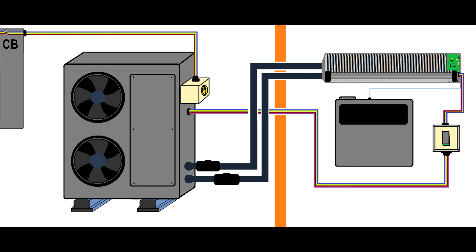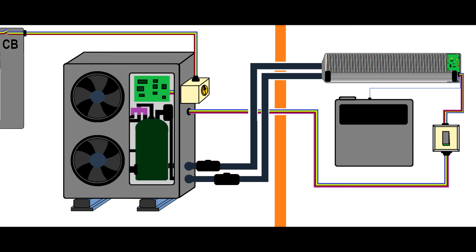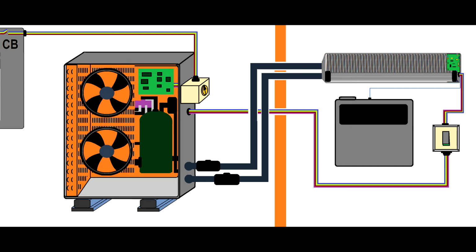If you take the lid off, you will find the printed circuit board and the evaporator, like you'll see here. So you can investigate if there's trouble with the AHUs, electrical troubles. Now, if you want to strip the outdoor, you take the panel off, you look at the compressor first, the printed circuit board, the three-way valve, and you see if there are any faults there. If you need to strip it more, probably you pull the entire front panel.